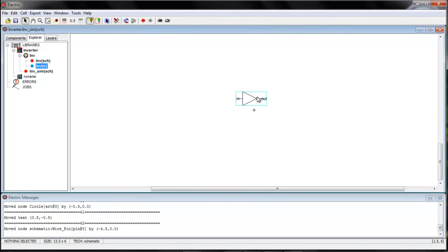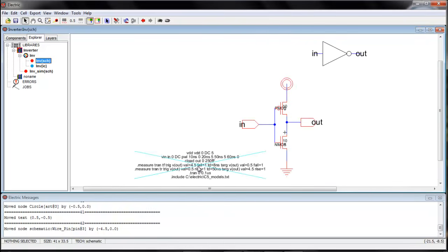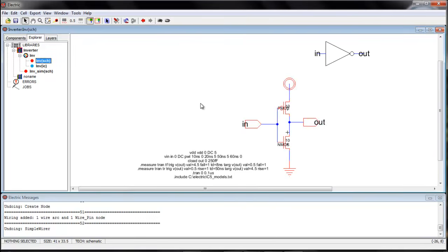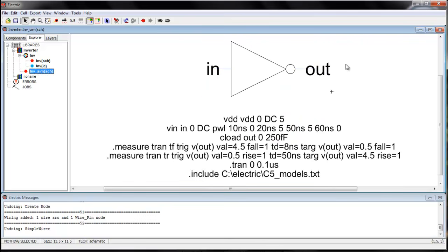Now I want to simulate only this icon. Now this icon will have the same properties as this inverter. So I will copy this code. So this is the code that I have just pasted. But now this V in and out, in and out is the input and output signal, of course, but then that belonged to this particular schematic. We had these exports, right? Here this in and out is of the icon. We don't have any in signal or out signal for our schematic here.